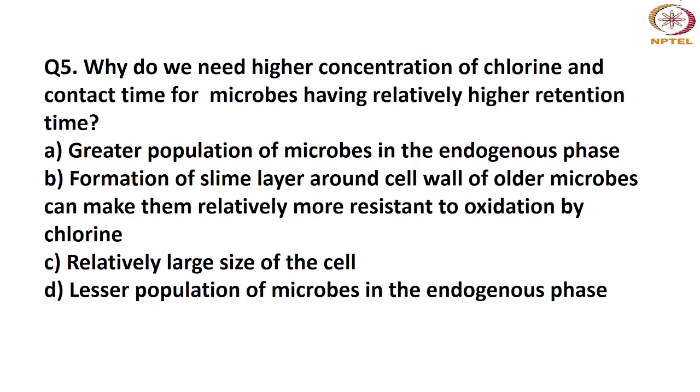Okay, I got another answer from Amol. He's saying it's B, right? So B is the correct answer. Formation of a slime layer around the cell wall of the older microbes can make them relatively more resistant to oxidation. That's why we need a higher contact time and higher concentration of chlorine, right?